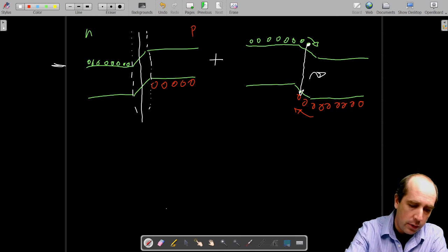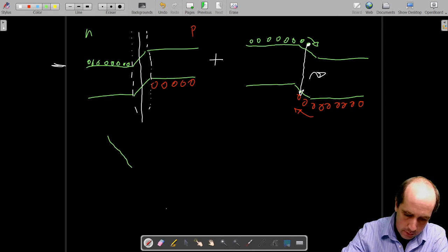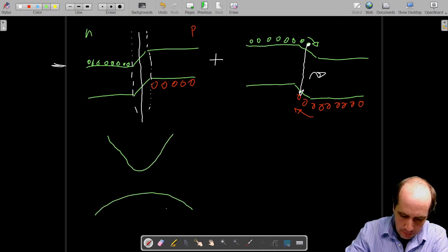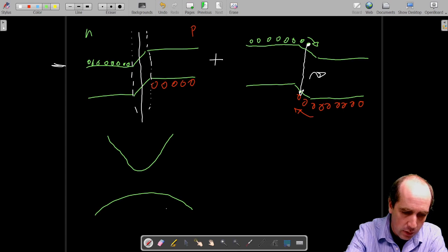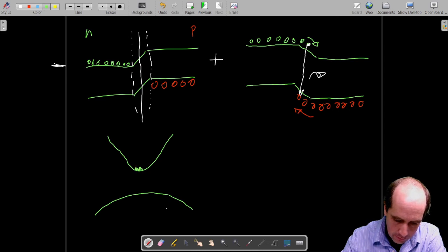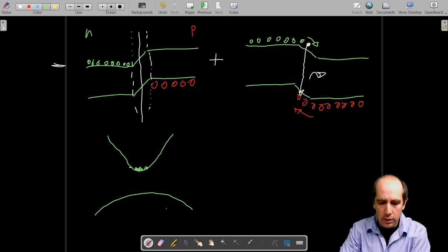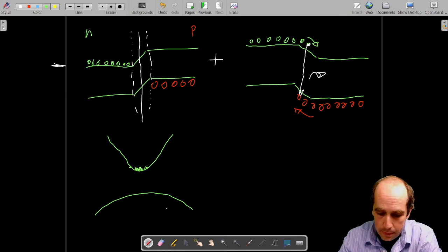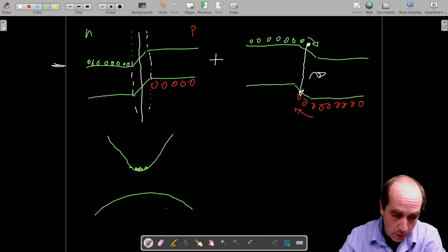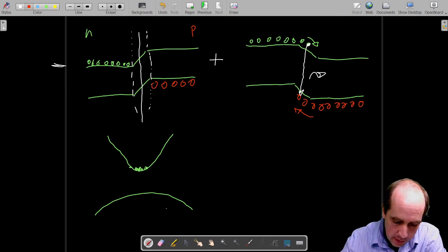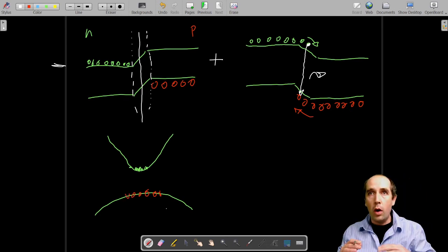The energy of the, if I draw the band structure in K-space, what we have is that we will have electrons over here. So these states will be populated, at least the bottom of the conduction band, in the region of the depletion zone, and also there will be a series of holes that are also electrically injected and which will tend to occupy the highest state.